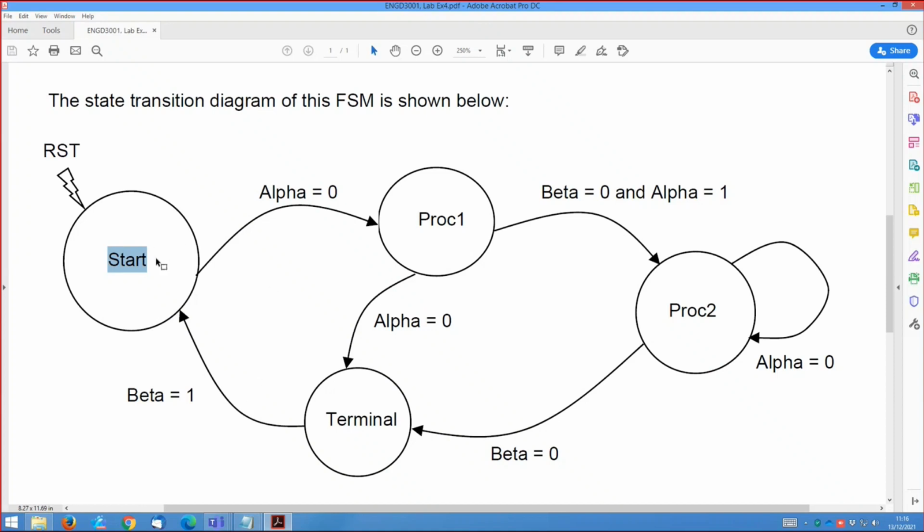And it is always best to test as extensively as possible. So it would be nice to set those signals in such a way that we stay in a given state for a few clock cycles whenever possible. So bear that in mind as well when you design your test bench. So that's pretty much it, really. That's what you are expected to do in today's lab.